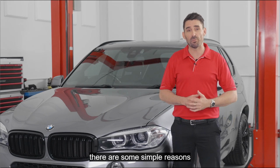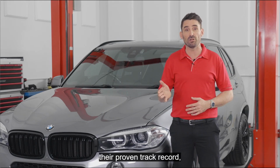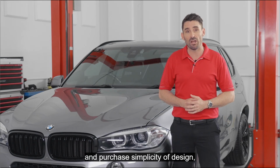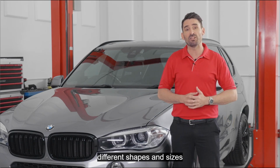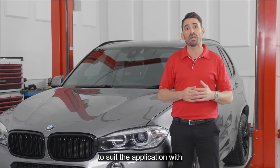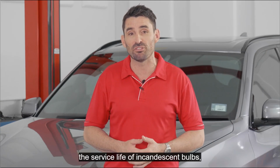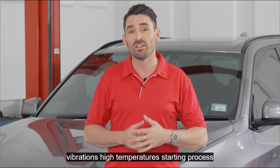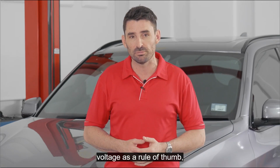There are some simple reasons why incandescent bulbs are still used, such as their proven track record, low cost of manufacture and purchase, simplicity of design, decent service life of the bulb, and the ability to make the bulb in different shapes and sizes to suit the application with ease. However, the following factors can have a negative impact on the service life of incandescent bulbs: mechanical loads through impact and vibrations, high temperatures, starting process, voltage spikes, and excessive onboard voltage.